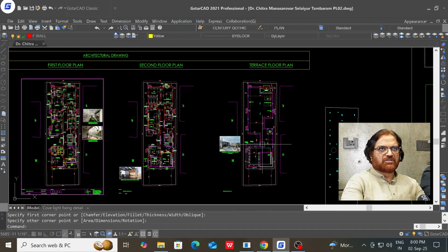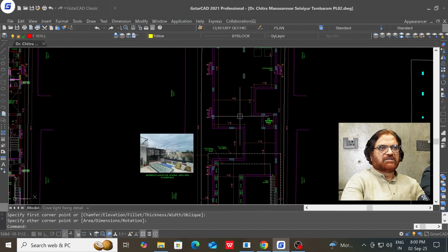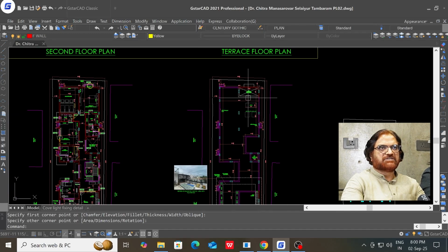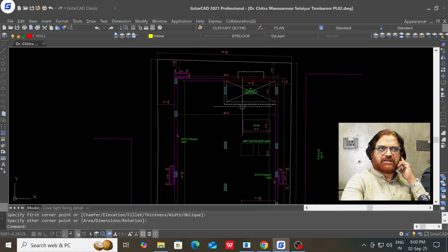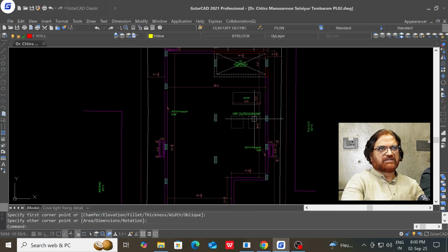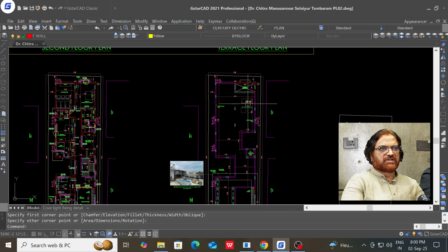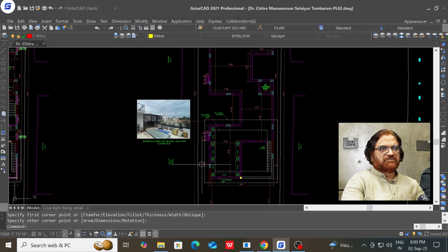After this, we go to the upper floor. We have mostly all the utilities on the upper floor. We have the water tank and water tank area. Below that, we'll have the pressure pumps and also the water treatment plants. Everything will come here, and the generator is located here, and the VRF air conditioning is located here. So all that will be fine tuned a little later.